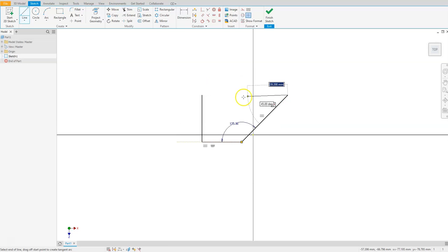Enter. And now I just want to make this come back to this area. So I can go ahead and apply and put this line right on that end point. You'll see that I don't have a horizontal constraint being applied to this, but I'll add that with one of the manual constraints at the top. So I'm just going to select this line, that end point, click there, and then I'll hit Escape.